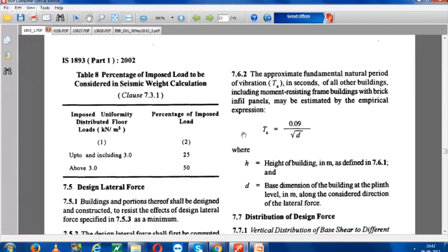In case of the Nepal earthquake, those earthquakes were long period earthquakes. That's why single story buildings failed. We used to say that if you have a single story building at your premises, it is very strong during earthquakes. Why? Because its fundamental frequency is very high, so the frequency of the earthquake cannot be matched with the single story building. But in the Nepal earthquake, the earthquakes were long period earthquakes. That's why more damage happened in single story buildings also.